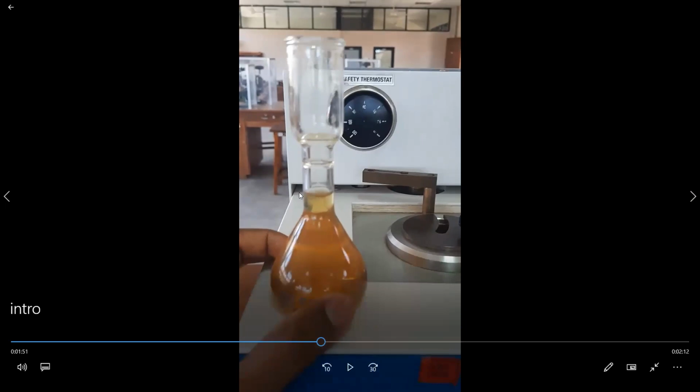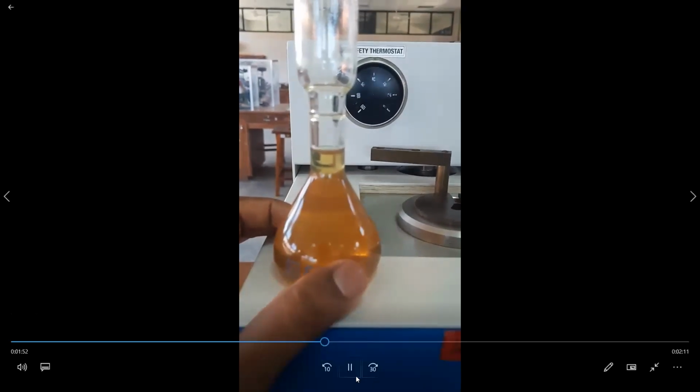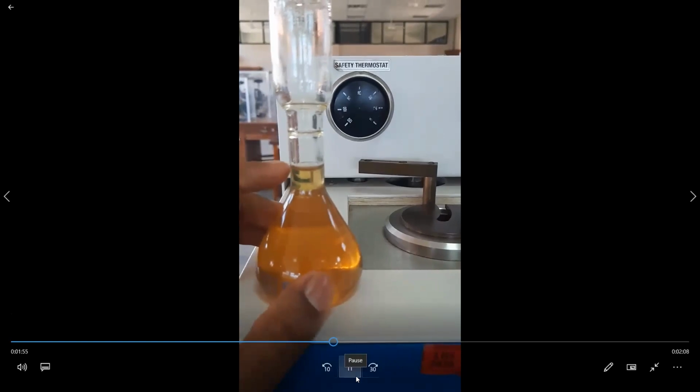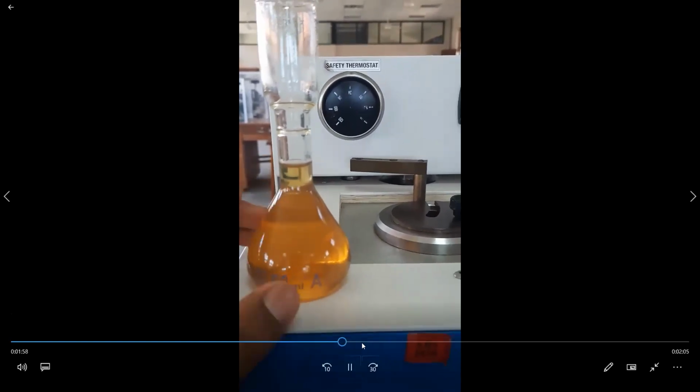You can see there's a limit, a mark. The volume is already marked, so we know how much 50 milliliters is. We should take exactly 50 milliliters, then put it into one cylindrical cup which we are going to use to measure the viscosity. When we are putting it in, we have to close that orifice, that hole, using the ball valve. Here you can see the marking point. Up to this is 50 milliliters.